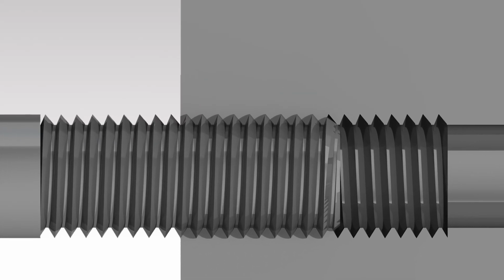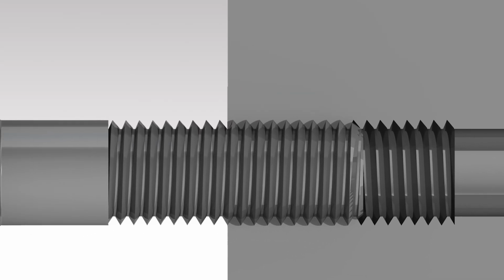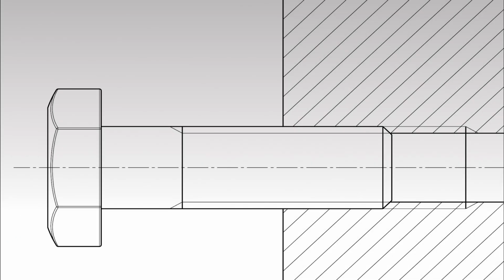An assembled screw thread is shown respecting the exception for cutting bolts in a section. The bolt with its external thread is drawn in the foreground, the hole with internal thread is shown in the background. The line indicating the major diameter changes from thick to thin where the bolt ends and continues to indicate the thread root in the hole. Similarly, the thin line indicating the minor diameter in the bolt changes to a thick line at the end of the bolt.